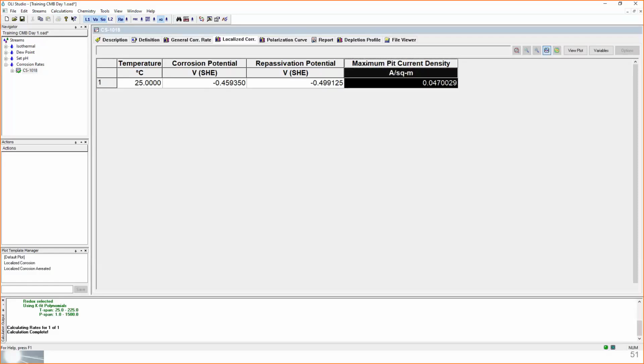And the third column is the peak current density that is being generated from the worst case scenario, from the worst case peak that you could have on that electrode surface. So in here it's saying that the maximum peak current density is 0.05 amperes per square meter. Because we are predicting localized corrosion damage, the peak current density that is predicted is this value. Okay? And again, I will spend more time next time explaining how to interpret these results.